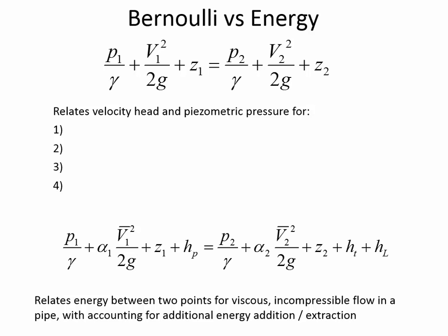Pressure is newtons per meter squared. Unit weight is newtons per meter cubed. And so that extra meters in the denominator pops up to the numerator. Everything else cancels out. So each term here has units of meters. So pressure head is the same.